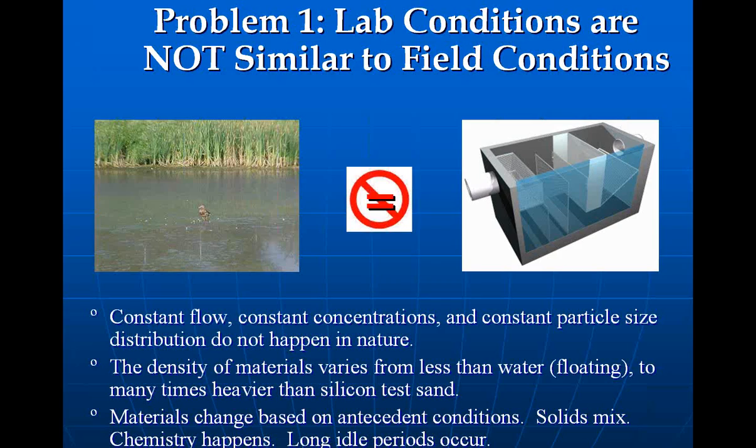With particle size distribution, smaller particles tend to wash off first. As velocities pick up in gutters and in pipes, the larger particles begin to move. And so the particle size distribution is also a constantly changing target. And storms don't simply start low, build up big, peak, and go down. They are all over the map as far as intensities, times, and delivery.